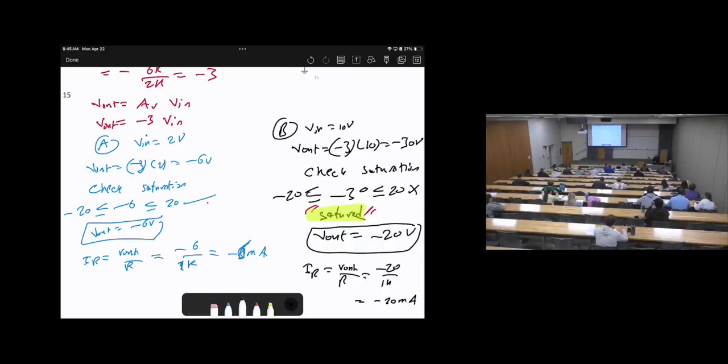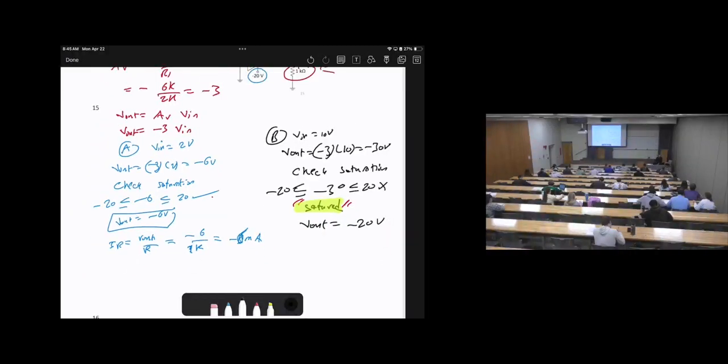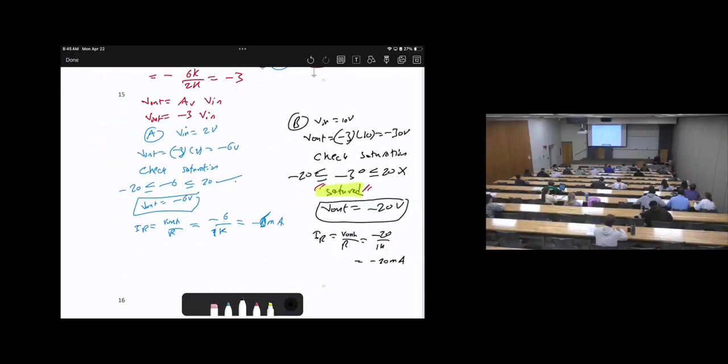Okay? Does this make sense? If you need to calculate the power, just I squared times R. You know how to do it. Or V squared over R, or V times I. You know V, you know I, you know R. So whatever formula is more convenient for you, you can use it. Any questions? So you see, it is simple circuits.